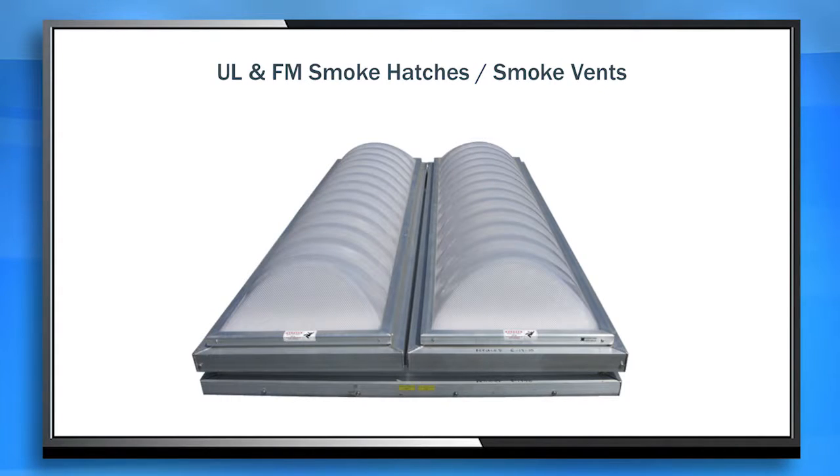We have a product called a smoke vent. A smoke vent is a product that you would use if, let's say, your local fire code required the skylight to actually open in the case of fire. And you may say, well, how do I make it open? The way we're able to do that is we have a fusible link. When the temperature in the building gets so hot from the fire, it actually melts and then it opens. And so we have that product that's called our Sunoptics smoke vent.